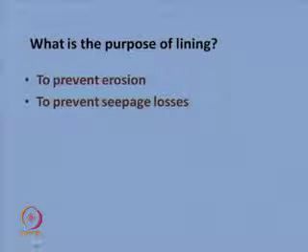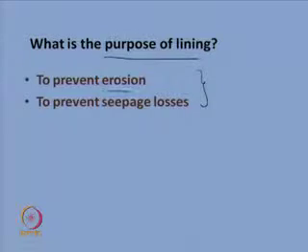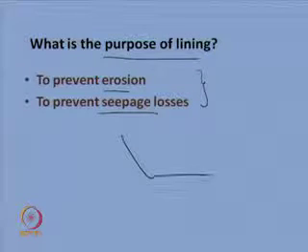As I asked you earlier, what is the purpose of lining? Now, in between this lecture, why do I need to pose you this question? Because, to reiterate, this is the design of non-erodible channels, you have to line the channels, and this lining is done to prevent erosion of the bed as well as the sides and to prevent the seepage of water into the channels.